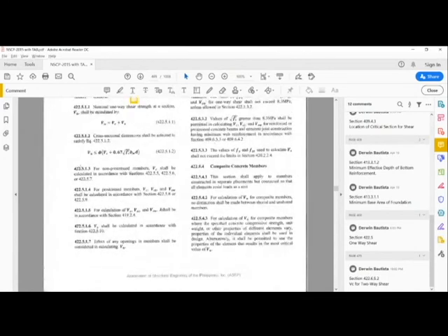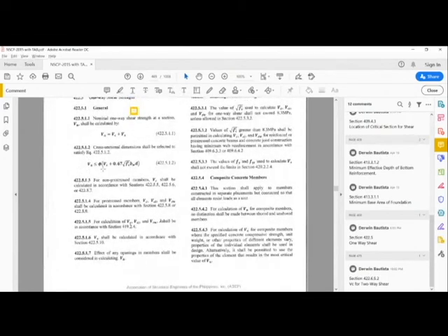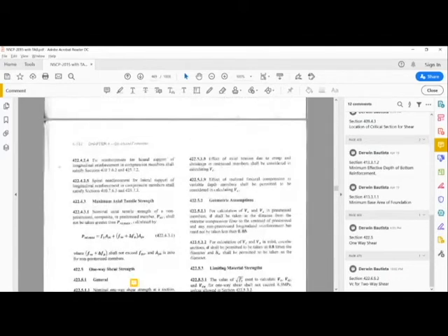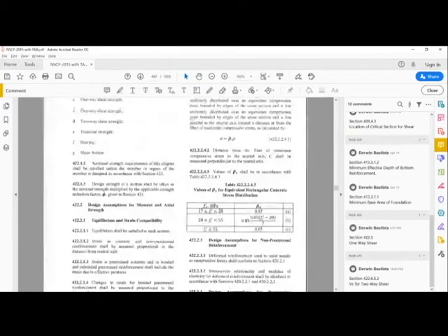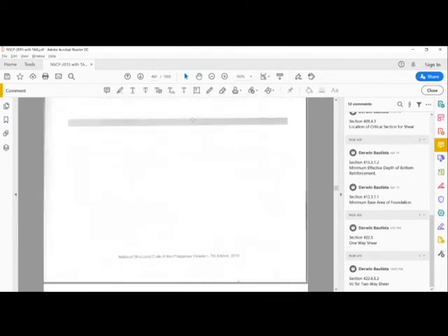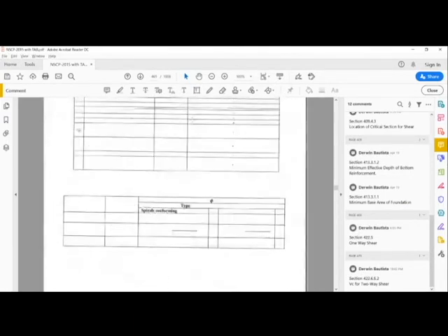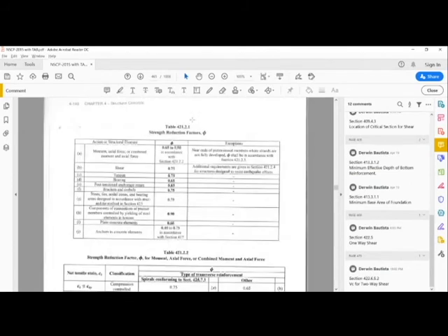Okay, so this is your formula for Vc, and your Vu is equal to phi. Yung phi natin dito is your reduction factor. So let me show you what is reduction factor. It's written here. So this table provides reduction factor, and we are designing for shear, so therefore the phi that we're going to use here is 0.75.